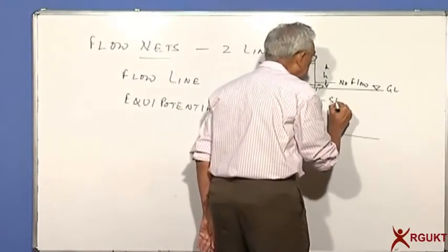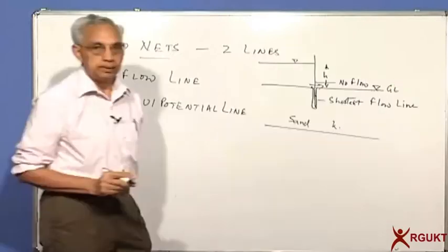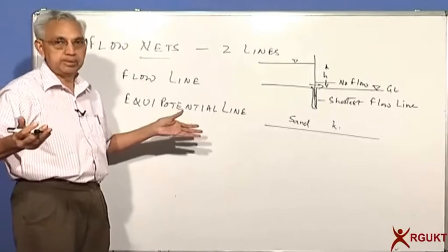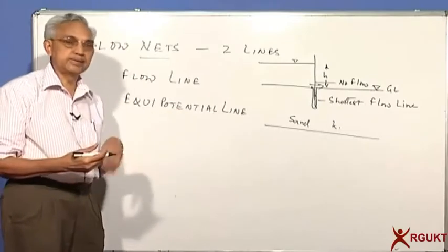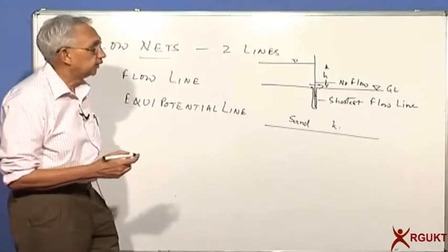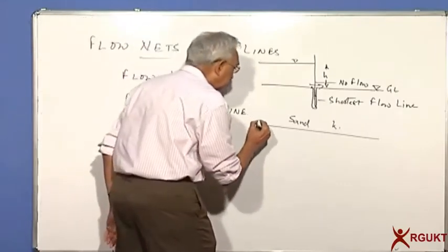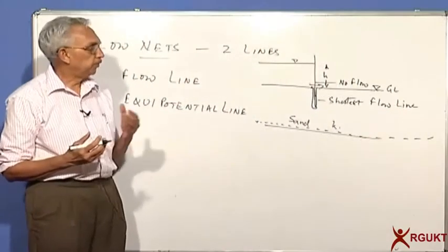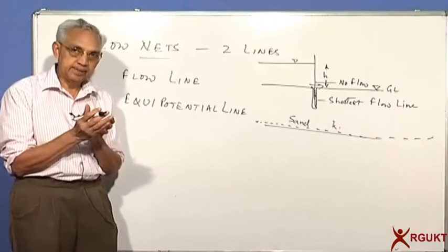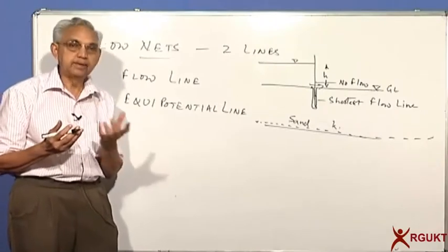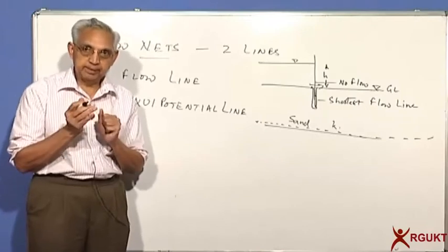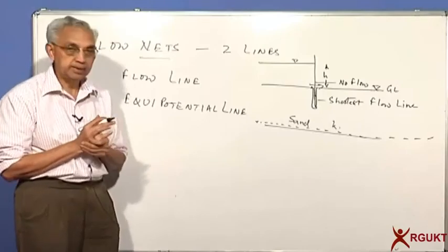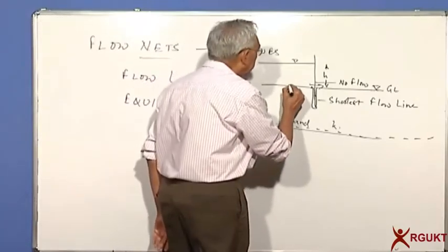As far as this is concerned, what will be the longest flow line? Just imagine this whole thing is a large deposit, obviously running into hundreds of meters or 1,000 meters. So the longest flow line would be along the bottom. So you can see that the flow is along a line. Can a flow line intersect with another? Obviously no, because the path has to be a steady state flow, and we are always talking of laminar flow and not turbulent one. Imagine another point somewhere in between.